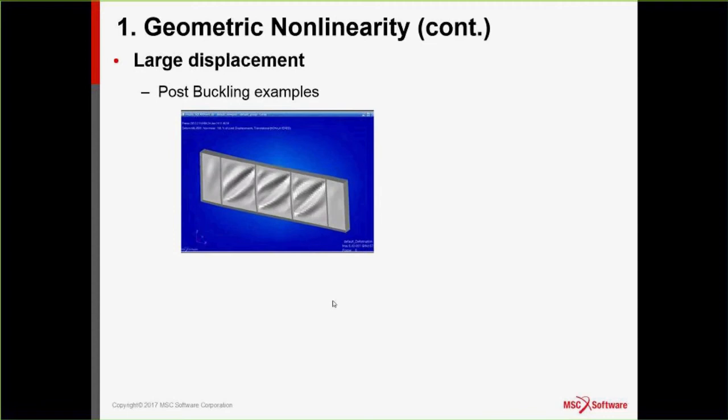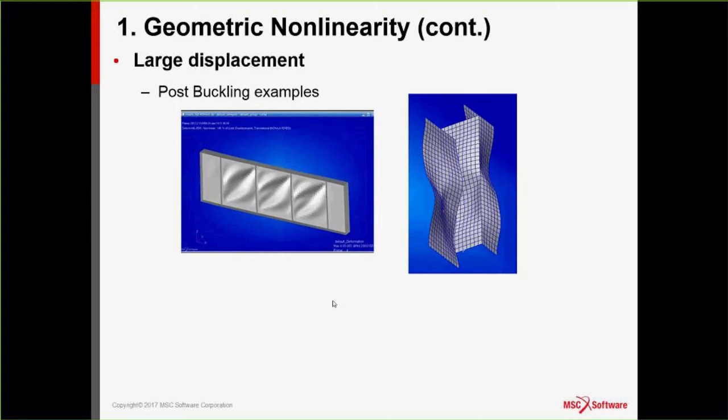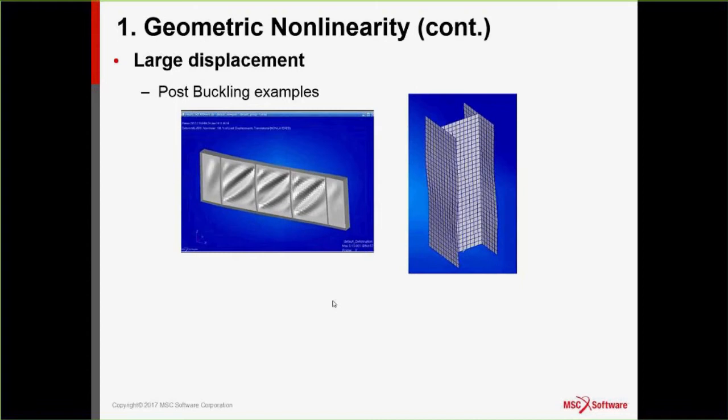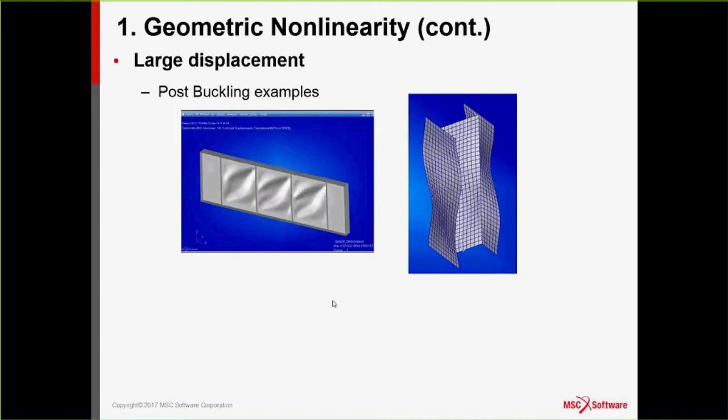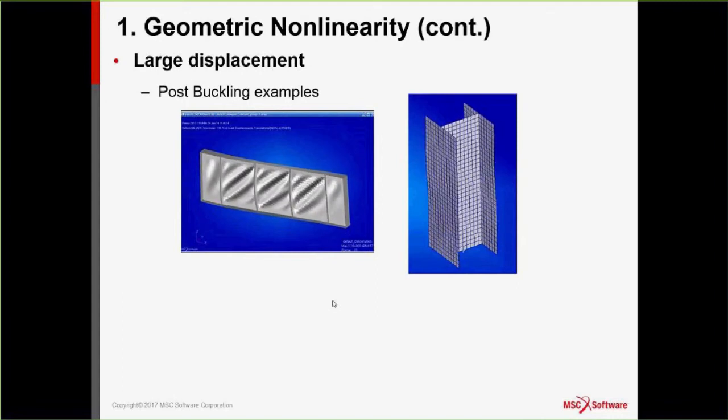So we do have to capture this with geometric nonlinearity. Another example would be this column right here. Again, you can see as I start to push on that, the flanges will buckle first. Again, you can get a closed form solution. I can calculate the linear solution.